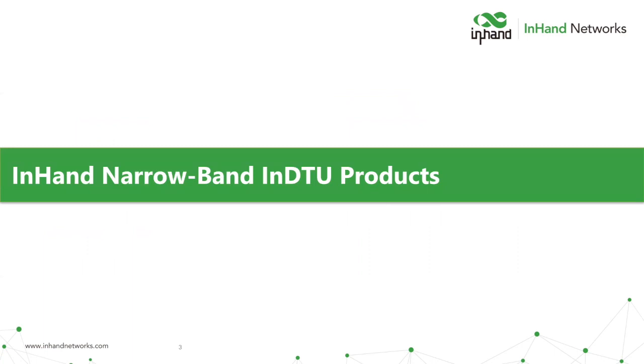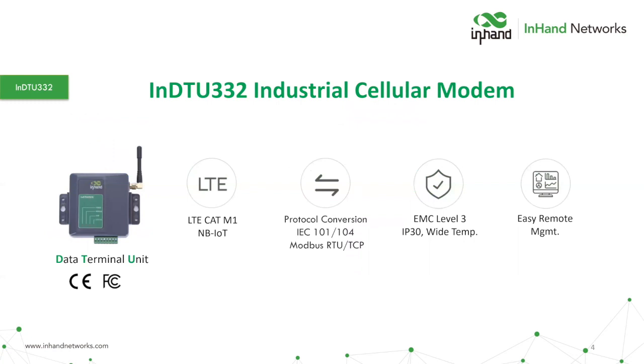So the narrowband product that we're launching is the NDTU. The NDTU332 is an industrial cellular router modem. If you're curious what a DTU is, it stands for Data Terminal Unit. So think of taking old legacy serial equipment and then converting that over to a WAN such as the cellular network. Just a quick overview, we have LTE Category M1 and narrowband supported on one SKU, protocol conversions, Modbus RTU to TCP, IEC 101 and 104. It's essentially the European version of DNP3 for those of you familiar with grid protocols. It's EMC level 3, IP30 with a wide range of temperatures, and we have a lot of different easy remote management tools.